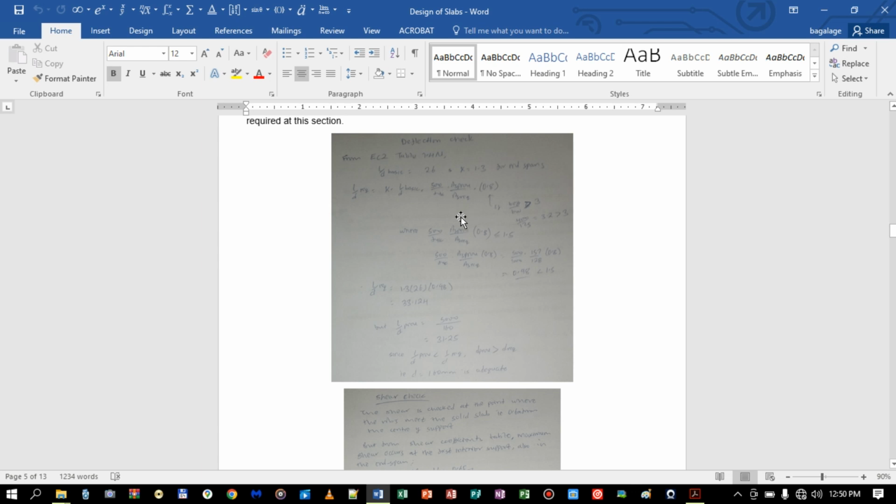The other thing that boosts the ability to resist deflection is the section. The fact that we designed for a T section at mid span, there's a factor we multiply the basic span to effective depth ratio with. All these factors are in Eurocode 2, in that very section for checking deflection.